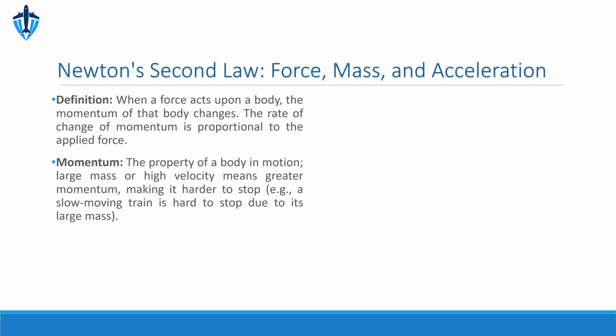This formula is vital in aviation for calculating thrust. Here we have a specific derivation for thrust which accounts for the change in air velocity over time. This formula is force equals weight times the change in velocity divided by gravity times time. Let's look at a practical example.